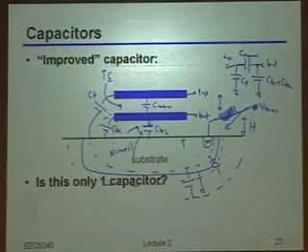Now, if I've done things quote-unquote right, and this is why I needed this big resistor here, what I'm really trying to do is make it so that this capacitor shows up in series with that junction capacitance. Not only that, I'm trying to make this junction capacitance as small as I can by basically biasing the heck out of that diode. So the reason I needed this resistor was so that I can actually apply that bias, but do it in a way that doesn't create an electrical connection directly to that node, which would mean you just directly get that bottom plate capacitance there. Okay?